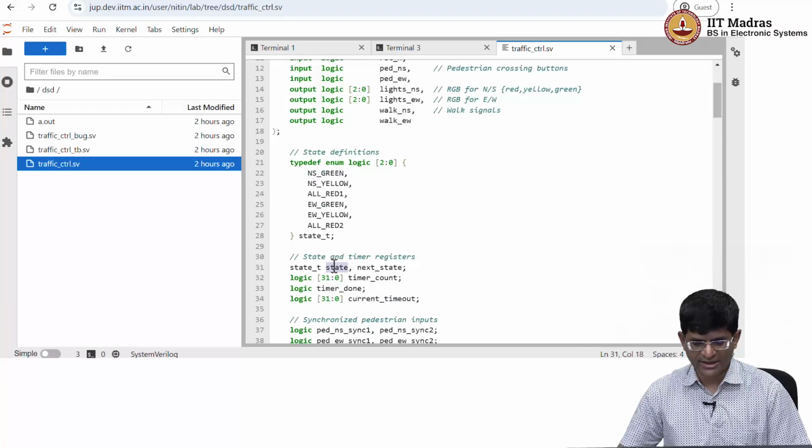Okay, so we have a state and next state. Previously we talked about current_state and next_state. It is also common to just call it state; I do not necessarily need to have it as current_state. You might also have something like FSM_CS to indicate current state and FSM_NS for next state. There are lots of different conventions that are followed. Most of them are fairly obvious when you look at the code. What is important is that you recognize the patterns rather than going by the specific names that are used.